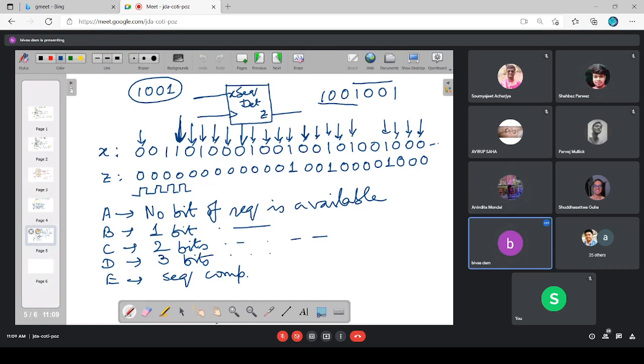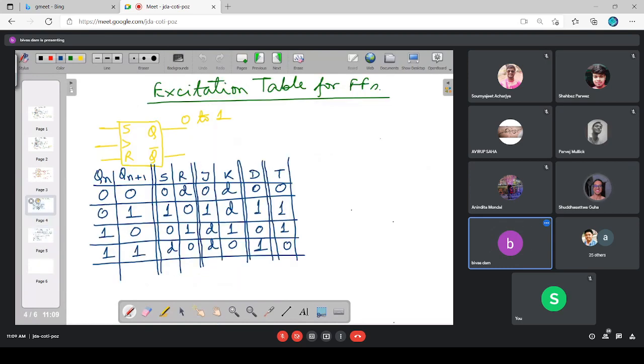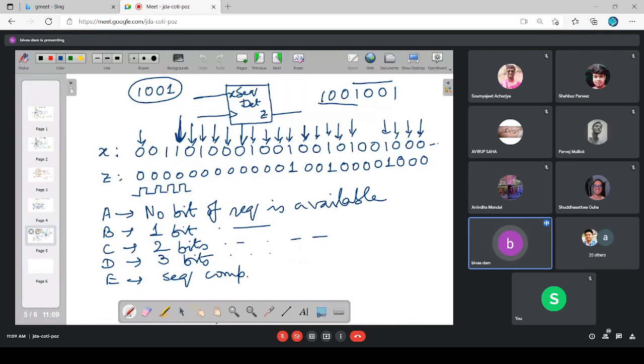5. So each state, and the earlier state we wrote in the table, are they the same or different? I'll come to that. That was the state of one memory element. This is the state of the memory element. Memory element state is 0 or 1? Now I'm talking about the state of one sequential circuit, sequential system. So that state is nothing but the binary encoded history.